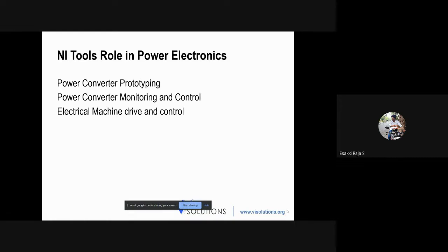So it can deliver 500 volts. This is one of the case scenarios where this power converter comes into the picture for EV. One is to reduce the battery size. If we want more voltage, instead of going with a larger number of battery cells, we can reduce the number of battery cells and boost the voltage using a boost converter. So this is one scenario.